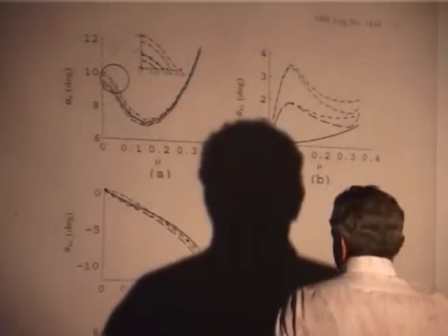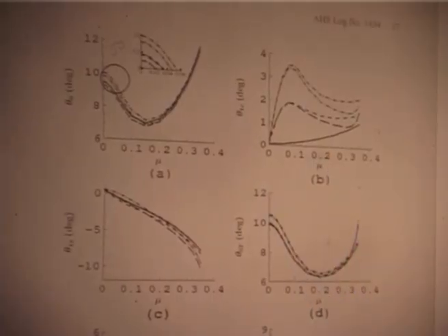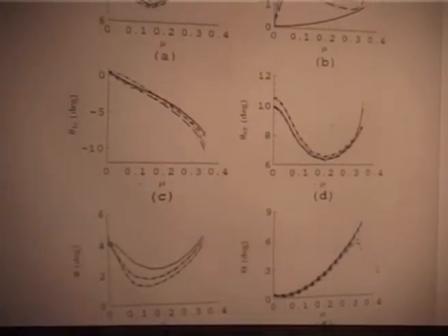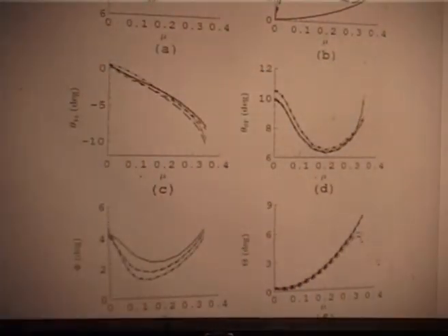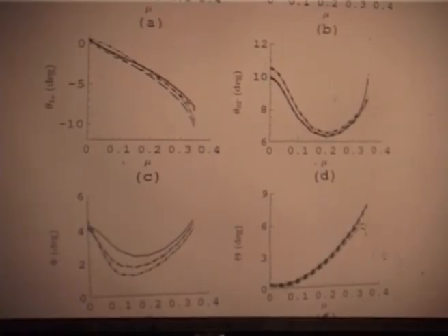And of course, the tail rotor follows a similar trend as the main rotor, okay. And these are roll and pitch, but for roll attitude I do not have data to compare with experiment, because I do not have data for this with a real helicopter. So, anyway, once we develop it, HAL will be using this code, because you can't measure it unless you have some other mechanism. What is the rotor tilt angle, you should measure it and then plot, because the tilt angle depends on where you put your tail, what happens, etc.